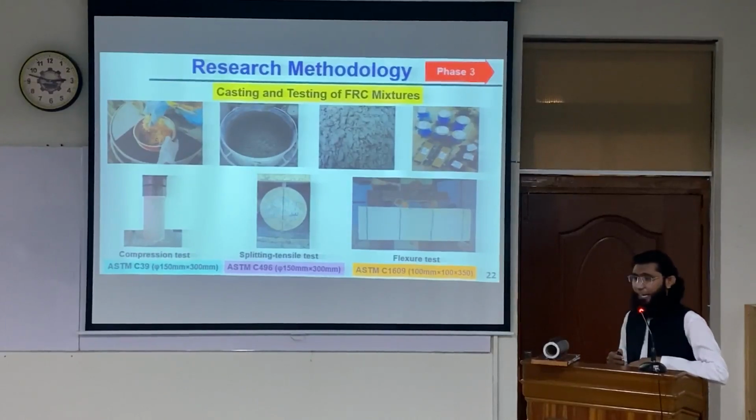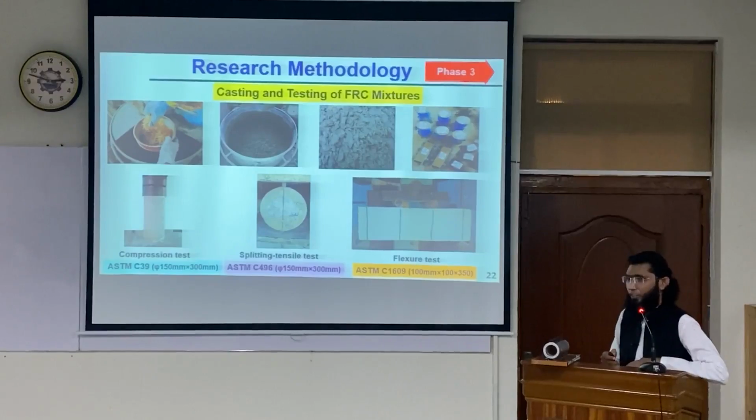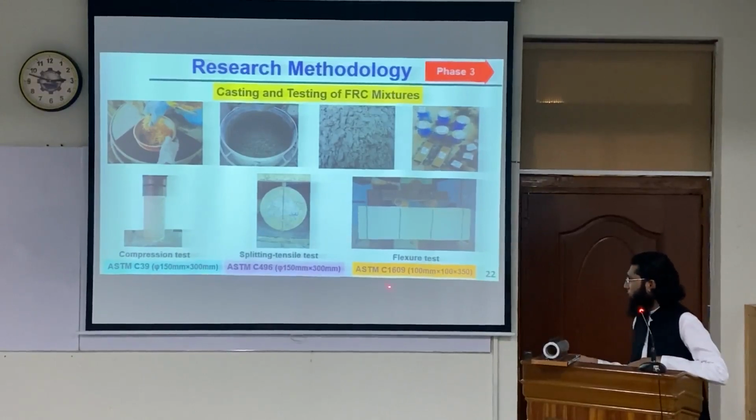And the third phase was the casting. So this was the casting and testing of fiber-reinforced concrete mixes. The cylinders and the prisms were cast in the lab and tested under compression, splitting tensile strength, and the flexure test according to the relevant ASTM standards.